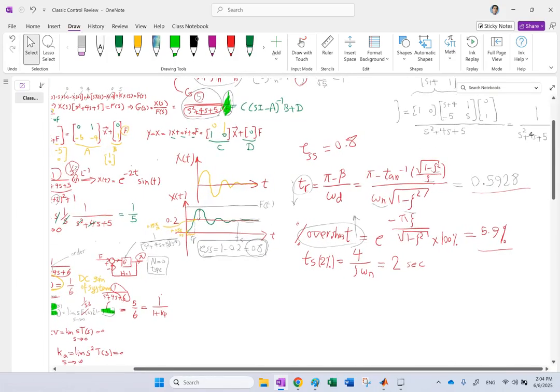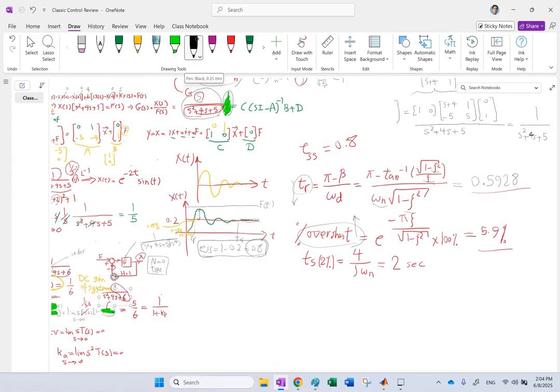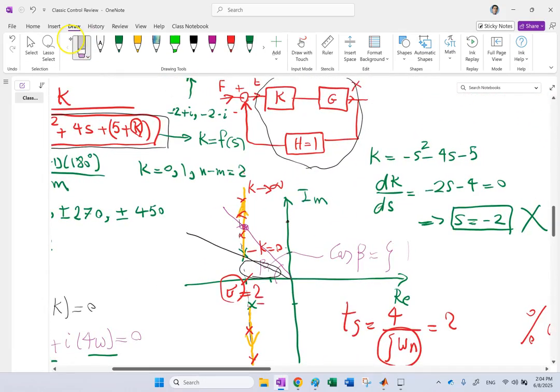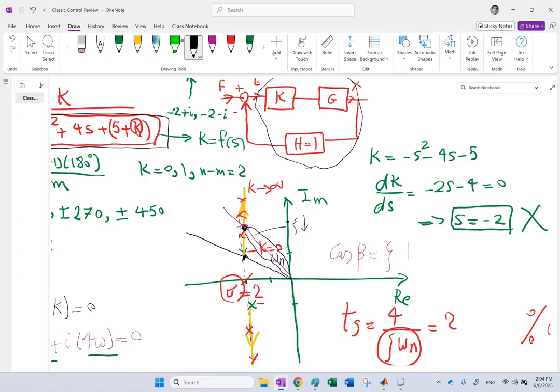For instance, they might say, well, make your overshoot go to some bigger number, but when it happens, what would you gain? Because if I get a bigger overshoot, let me clean up here a little bit. If instead of this point, I go to here, I have now a smaller xi. Okay, so this one has a smaller zeta. But what does it have bigger? Well, remember this radial line here, that is omega n. So this one here has a bigger omega n.